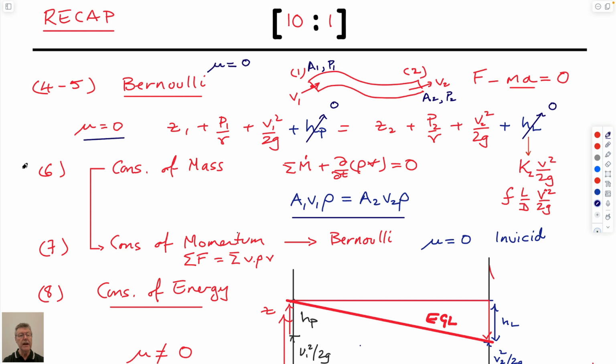When we looked at the more general conservation equations, we looked at 3 different equations. One was for conservation of mass. It was really an extension of this steady state one. This just says if you have a bucket, the mass flow rate in is equal to the mass flow rate out. If they don't balance, then they accumulate. So we need to have a more sophisticated term to do that. And we write this equation in terms of Reynolds transport theorem. We look at the sum of mass rate in equals mass rate out, and we have a special sign convention for that, which you'll all remember.